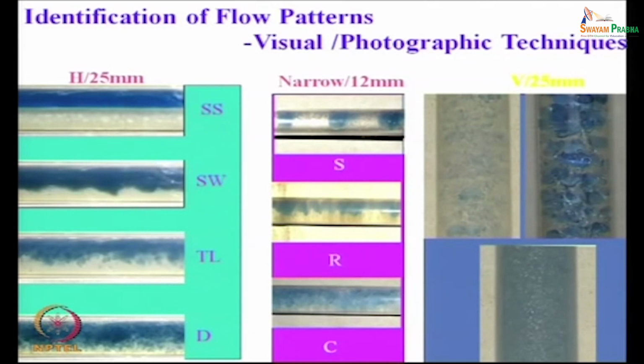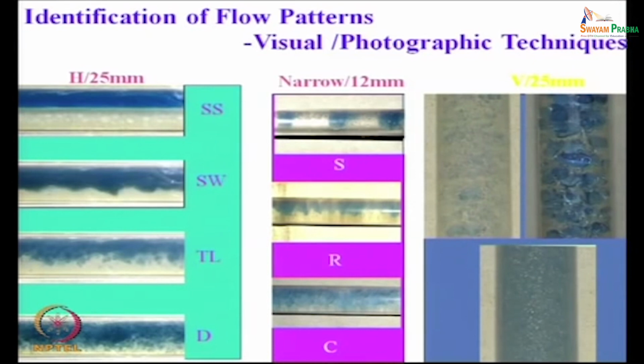So, generally for gas liquid cases, under normal circumstances, we have the bubbly, slug, churn and annular flow. In this case, we have the bubbly flow pattern, the inverted bubbly, in other words oil in water bubbly flow pattern, water in oil bubbly flow pattern, and then we have the 3-layer flow pattern. These are the differences which we did not have there. Just by replacing the air phase with another liquid phase, a low viscous liquid phase, we find these ranges of differences.